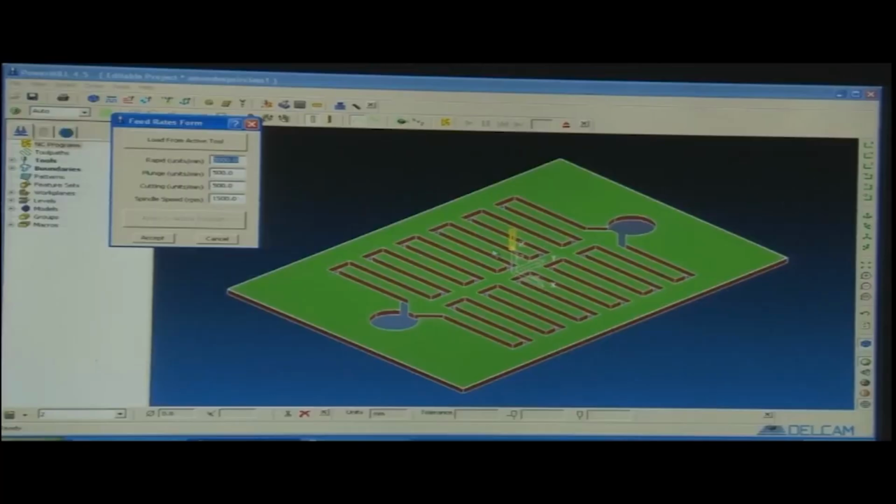For instance, if we use rapid speed from a far-off distance, the tool can come closer to the workpiece at rapid speed, then it can start machining. So, this rapid speed would save time, which is very important. We need to put some values here. The rapid is the speed in so many units per minute: how rapidly it would come close to the block and start machining. Here, rapid is 3000 per minute, and plunging is actually the final machining.